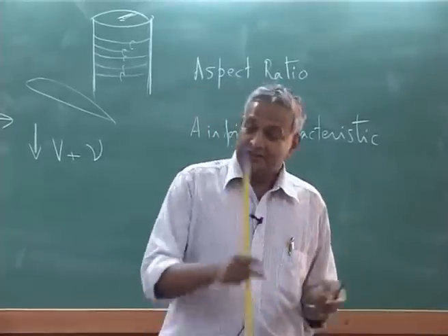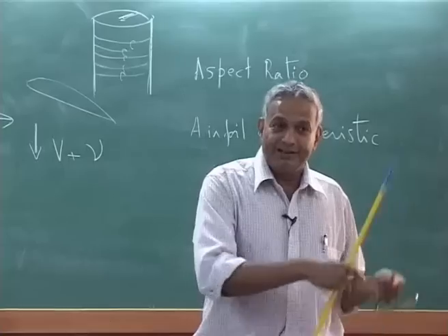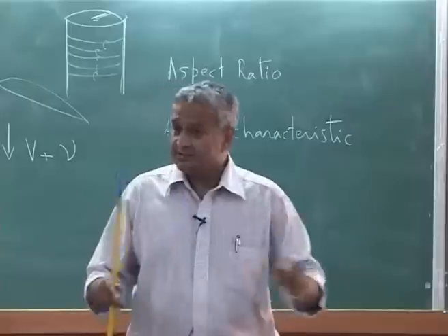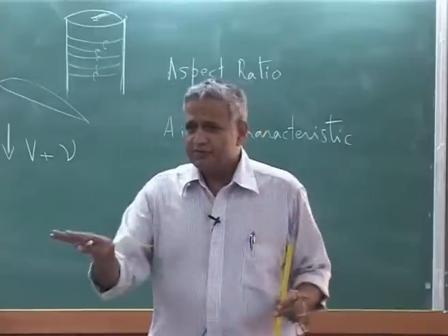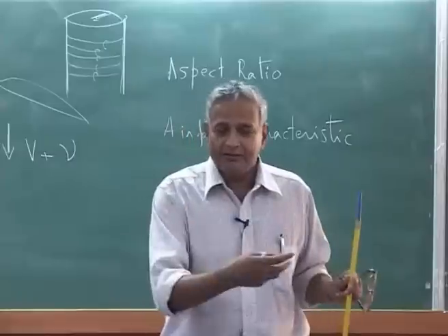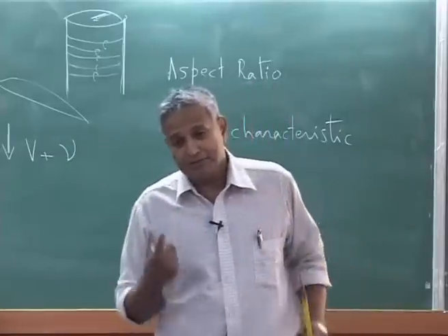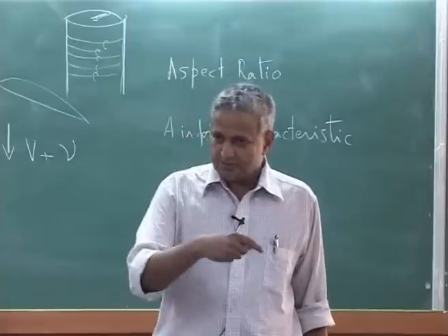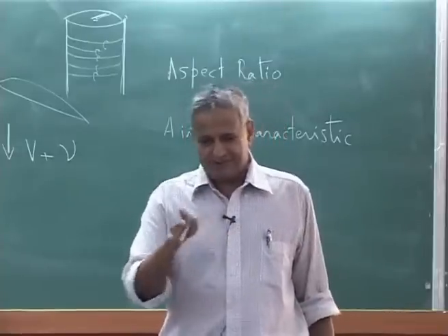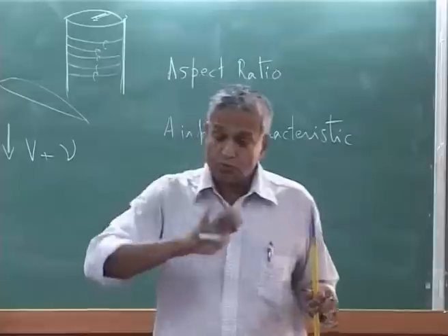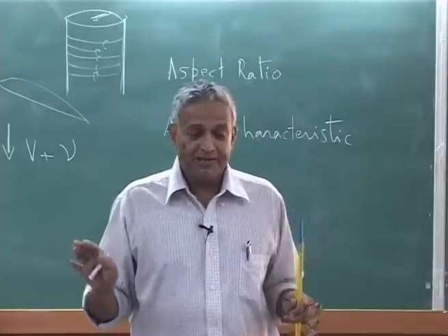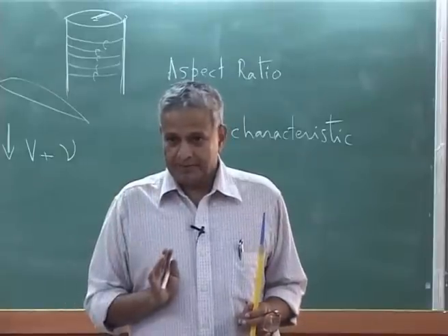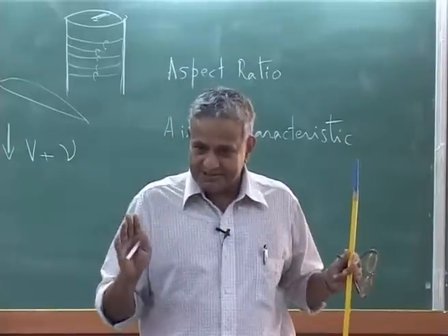But if you are working on aeroelasticity, loads, stability, etc. of the vehicle, you need to know the inflow. You say I will calculate by momentum theory, which is easy to incorporate. Of course that will be approximate, but it is not too bad. It still gives results which are quite close, but of course there are always differences.